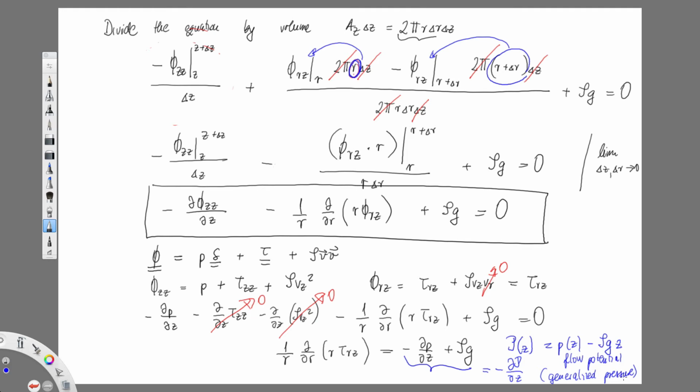So whether you have a plus or minus associated with rho g depends on how your coordinate system is pointing with respect to your geometry. Okay. So here both g and main flow velocity are pointing in the same direction. So my z and g are aligned. If they're not, you're going to have a flipped sign.